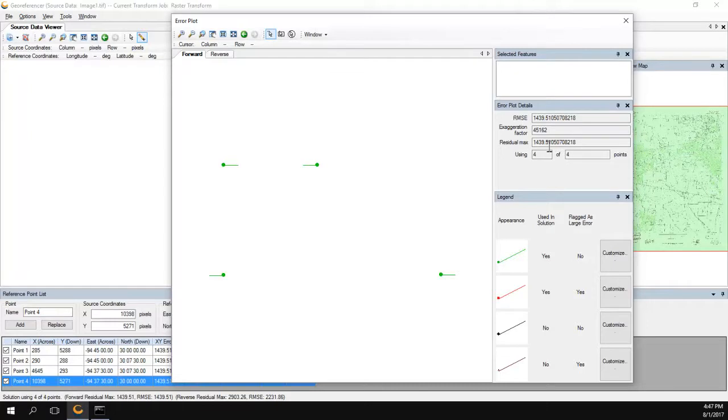We can't quite identify which point that's related to yet because we only have 4 control points, so that makes it a little bit harder to tell. But if we start to look at this, we can see that this is a very regular pattern here. Something is wrong. Our further north values here are pointing inwards. Southern ones are pointing outwards. Something's off here. Very regular pattern in terms of the direction and also non-uniformity in terms of the distances.